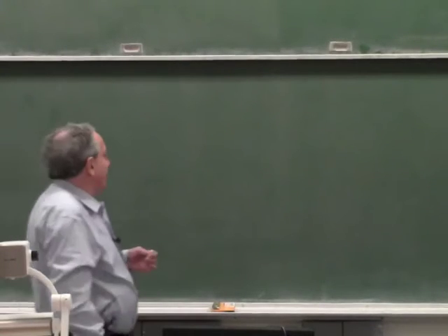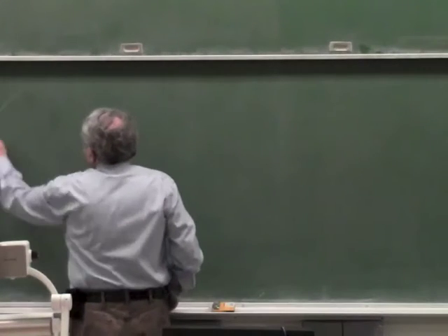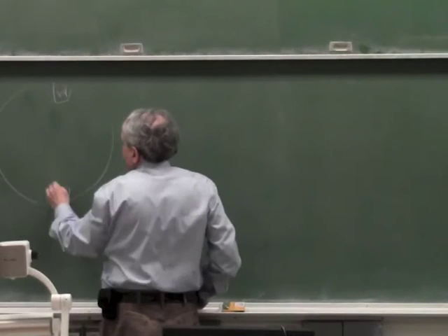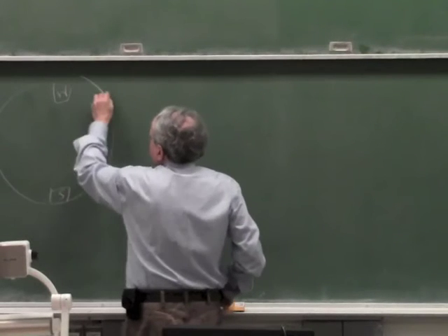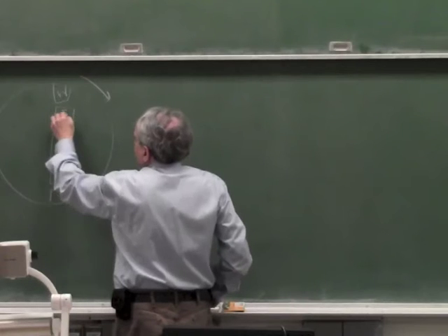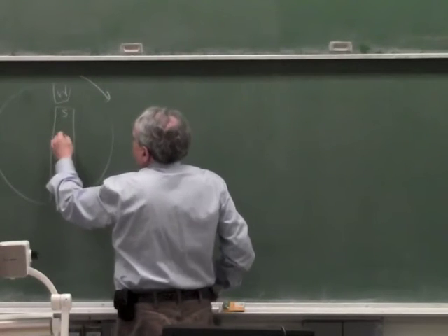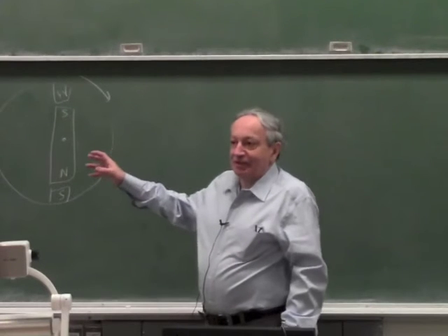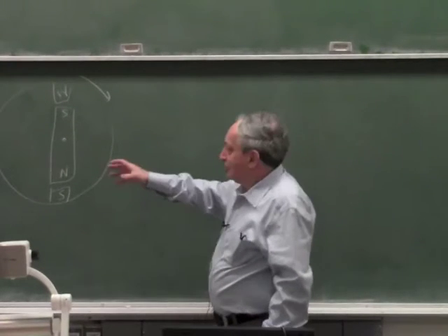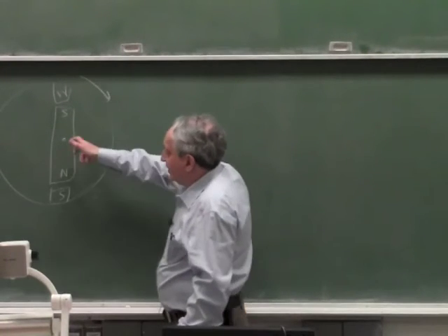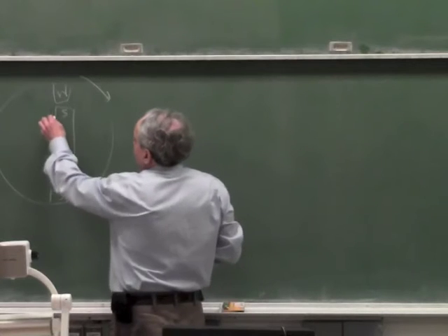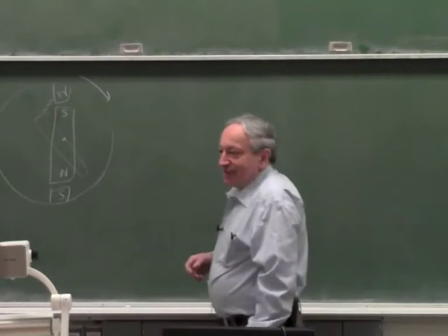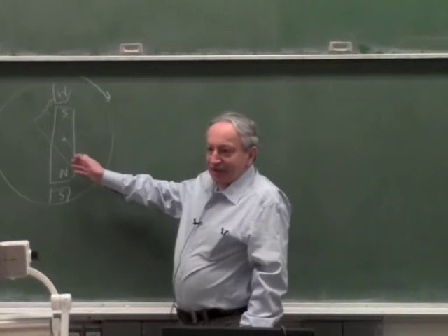because in a synchronous motor it's actually quite clear what's happening, because in a synchronous motor you have the equivalent of magnets which rotate, and then you have an armature which is attracted to the rotating magnet and dragged along with them. Okay, so it's very easy intuitively to understand what's happening in a synchronous motor, because you just envision this is a rotating field, it drags the armature with it, it drags it with a little bit of a spring action, which is called the power angle. It's the same as a stepper motor, right? So this is very clear.